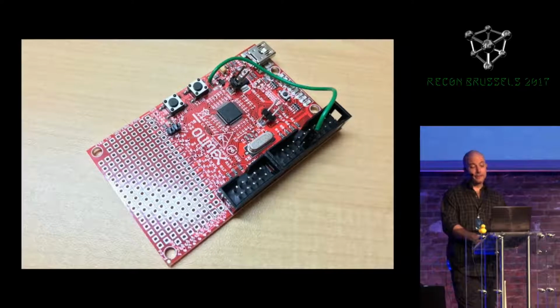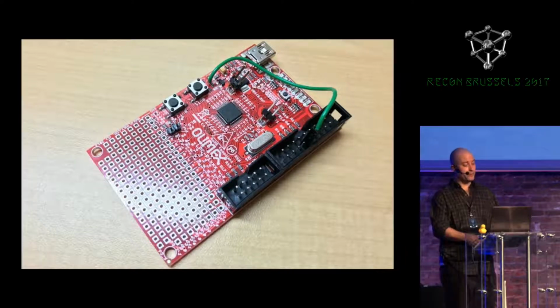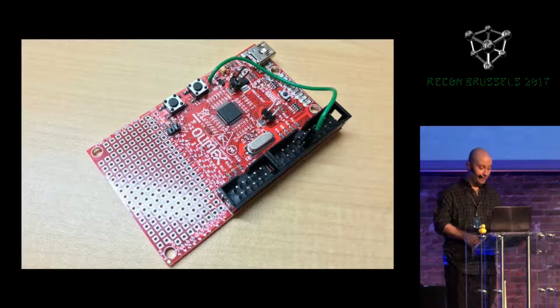And then another option is also to use a pre-made development board. This is an Olimex board for the LPC 1343 chip. This one has been modified a little bit. I've removed two of the capacitors, C1 and C4. These are the filter capacitors on the VDD pins, because I'm planning to glitch this chip, and that's going to involve quickly dropping out the power supply. So I don't want those filter capacitors. They're going to be trouble for me.